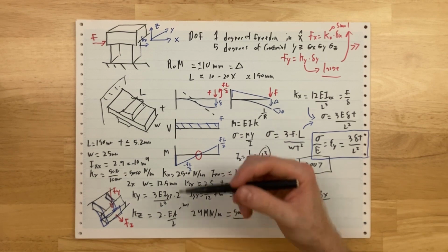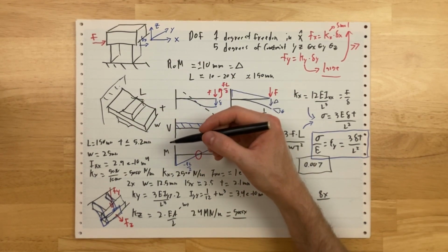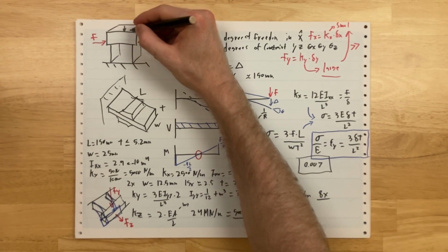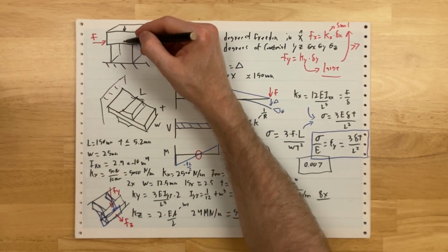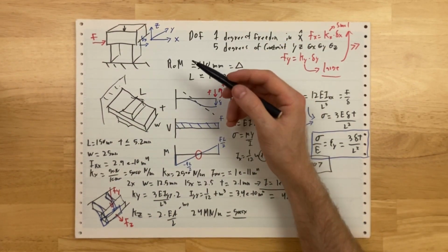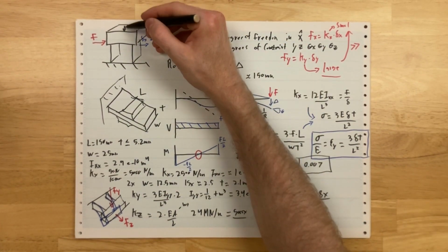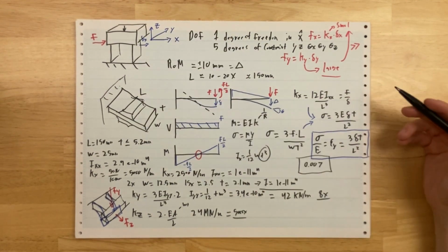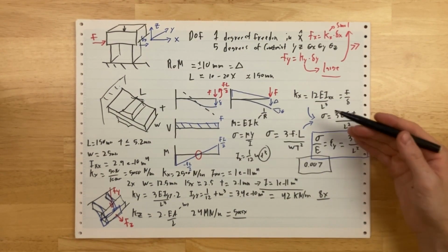So this means that if you're going to make a motion system, you want to be able to push it in x, but you want all the high loads to be in z. If you have high loads coming in y, you might as well rotate your flexure by 90 degrees so that they end up showing up in z. However, if you're pushing down in z, you're exposing these blades to buckling. So you actually have to do an Euler buckling calc to see, can they support those loads?